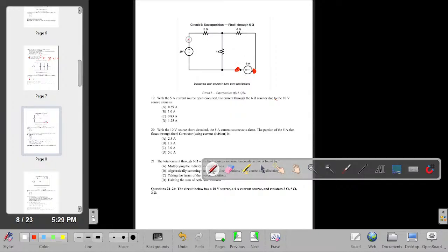So here you simply have to introduce your current I, right? Then you realize that the total current becomes this, and this and this being in parallel. So we are just trying to say that we deactivate the source. We are not going to consider the fact that we have opened it so that the current is not flowing. We are just trying to deactivate it. The only way to deactivate a current source is by opening it.